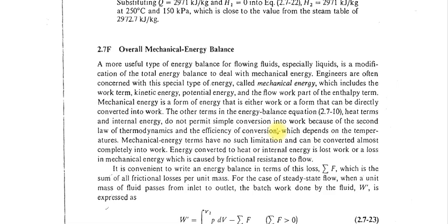And the mechanical energy will convert into thermal energy when you have a lot of losses, meaning your flow is very high, your friction is very high, or your fluid is very highly viscous. Under those conditions, the mechanical energy will convert into thermal energy. When the fluid is flowing, you will see the fluid start to heat up because the kinetic or potential energy is converting into thermal energy. Or you are increasing the temperature of the system in such a way that the density of the system is changing.